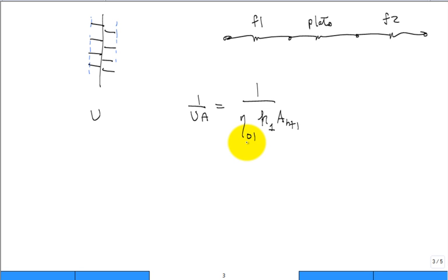Let me just try and highlight some things here. This overall efficiency, 94.3%. That convection coefficient, h1, 20.2 BTUs per hour foot squared degree F. And you can do it for 1/24 of the heat exchanger, or actually you could do it for the whole heat exchanger.